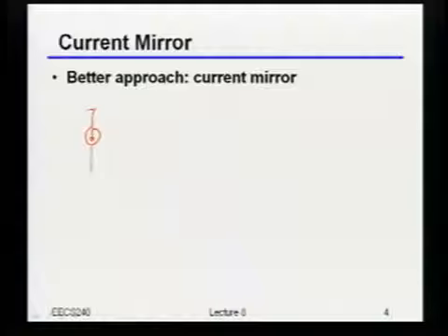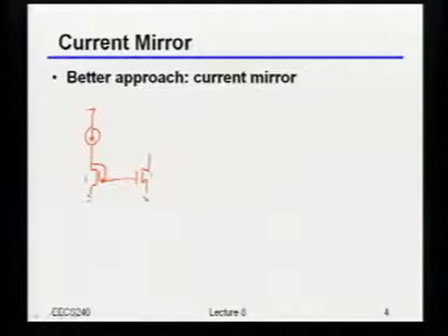Okay? So obviously, if I gave you some current and you trusted that current, then if I wanted to create a current source, I obviously just build some sort of current mirror. And again, this is nice because as long as the two devices are matched to each other, I don't have to worry about threshold voltage. I don't have to worry about things like temperature or the processing being a little bit off, right? Basically, as long as I can get the two devices to match each other, which I can do pretty well, I'm basically just going to copy that current.